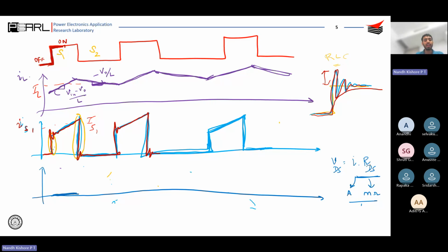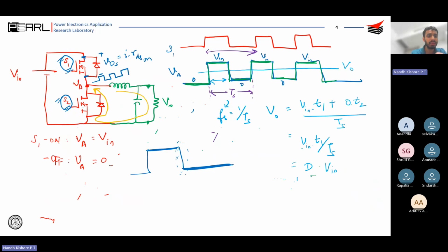And when the device is off, that is when this device turns off and the other is on, then what would happen? The voltage across the other device would be almost zero, so the entire Vin voltage is going to appear across S1. That is, the device S1 is going to block the entire DC bus voltage, or whatever is your supply voltage, Vin.